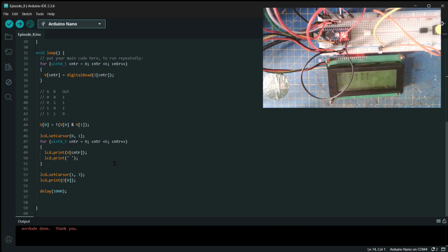Here, because I can turn the backlight on and off, I could make it flash in the code. I'm going to investigate how to wire that up to do the fading. It's really simple to do if you get the wiring right. You just use a command called analog write, and on an Arduino there's certain pins you have to use on the outputs for it. And you could say I want the backlight at 50% brightness, or 25%, or 75%. I will investigate that, and I will do that in another one.